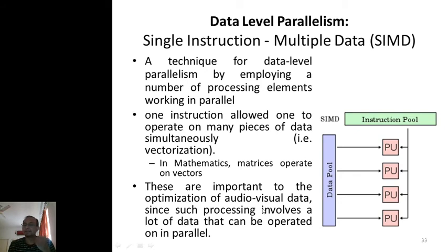In fact, the SIMD architecture was first introduced in the Pentium processor with the MMX extension, the multimedia extensions. Earlier, processors did not support multimedia, meaning audio video processing. Later on, multimedia extension support was added to the Pentium processors, and in that the SIMD concept was added. Now all DSP processors always have to process audio video or multimedia signals, so they always have SIMD inside them.